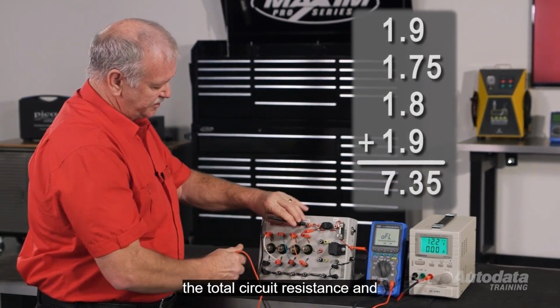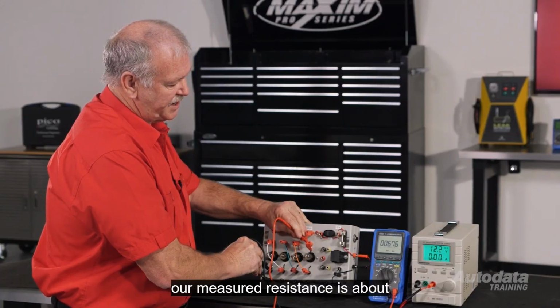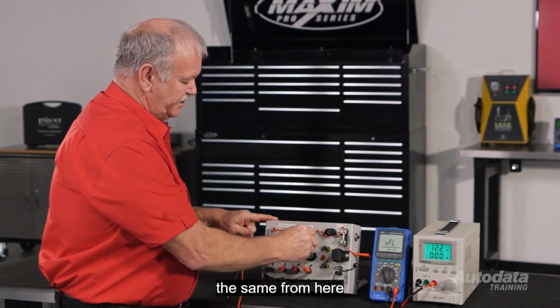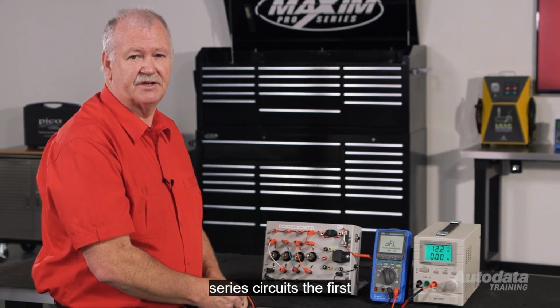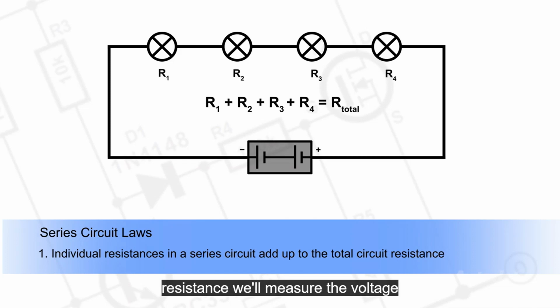And if I measure the total circuit resistance, our measured resistance is about 6.8 ohms. So you can see it's pretty much the same. From here we can start to formulate some rules that apply to series circuits. The first rule is individual resistances in a series circuit add up to the total circuit resistance.